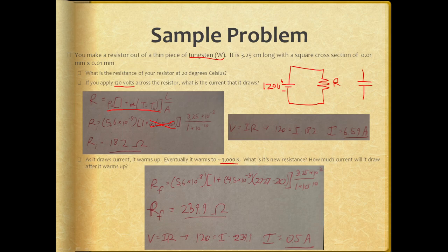So, our temperature is going to increase, which means that we now need to use the coefficient changing formula to adjust our electrical resistivity constant here. So, this piece of the formula, we still have R equals rho times length divided by area, but now we're going to be using the full modification portion of the rho formula to change it from its baseline rho.